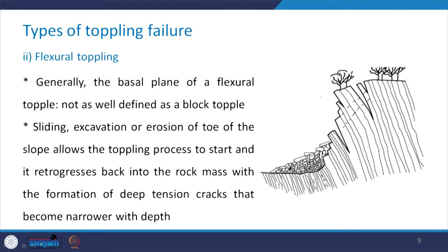Generally, in this case, the basal plane of a flexural topple is not as well defined as it was in the case of the block topple. You can see here this dark line, this is the basal plane, and you can see that it is not very well defined. Sometimes there is a separation and then sometimes it is like this. So, it is not very well defined. However, in the earlier case the base plane was kind of in a stepped manner.